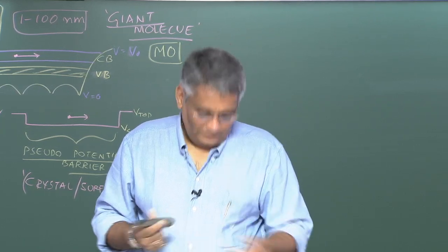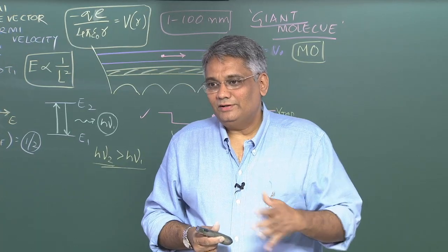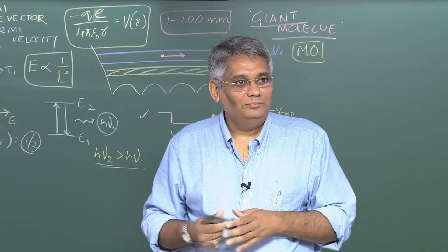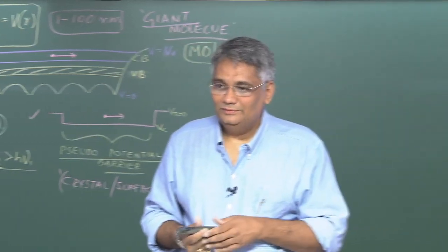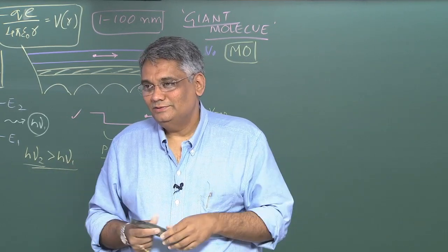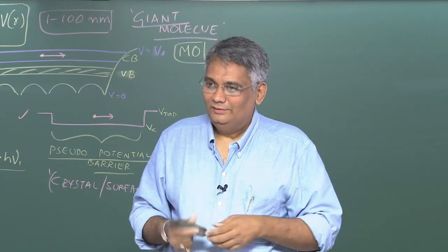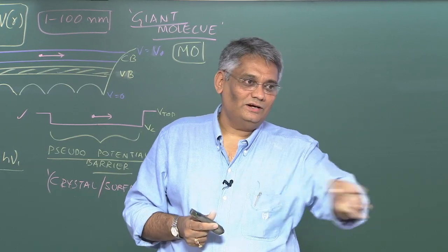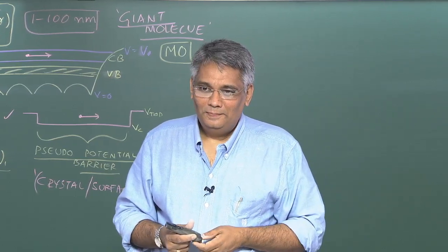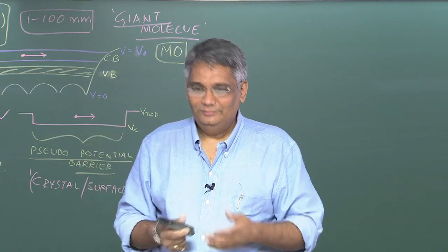You understood? Okay. So there is no better example. This can be done at the lab level in a very simple way to show the effect of size dependent quantum confinement. There is no other better example than this, because CdSe shows optical emission in the visible range at 630 nanometers. It luminesces in the red spectral range, and this red emission starts shifting towards green and blue. A beautiful example of band gap engineering, blue shift, everything put together.